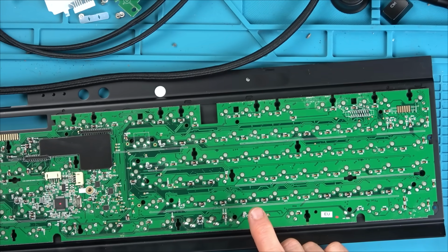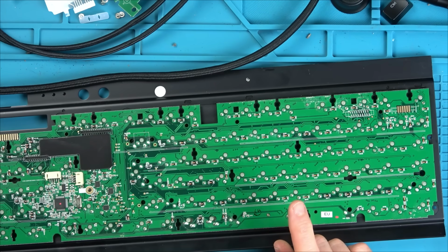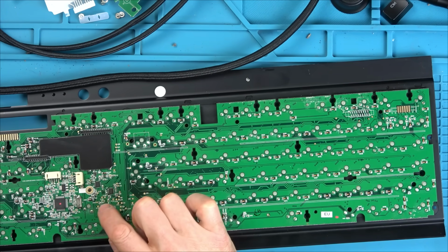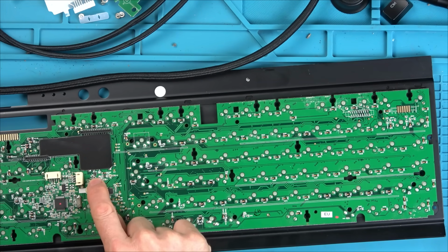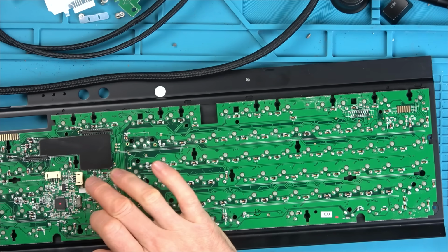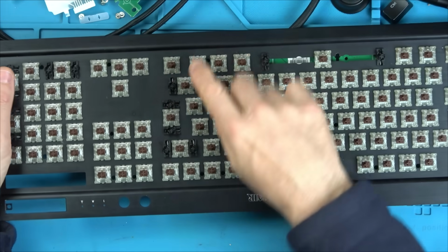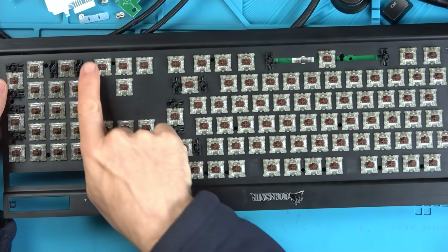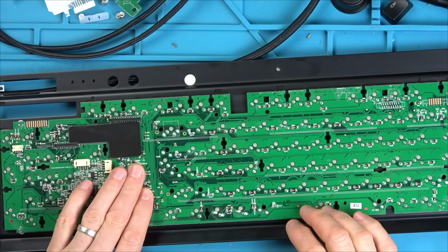So, unfortunately, I think that we have to unsolder every single one. But before I do that, because that's going to be really painful, I think I'm going to take these 3 chips off and put them back in a different place. So for example, take this one off and put it here, take this one off and put it here, and take this one off and put it here. And then if I plug it back into the PC and all of a sudden we have these here not working or these here not working, then I know it's something to do with the chips.